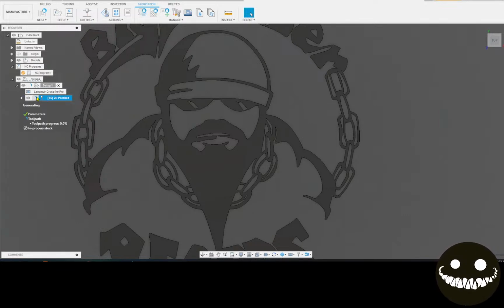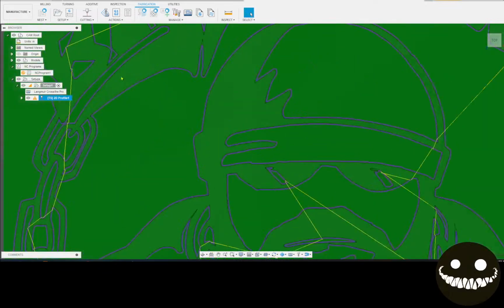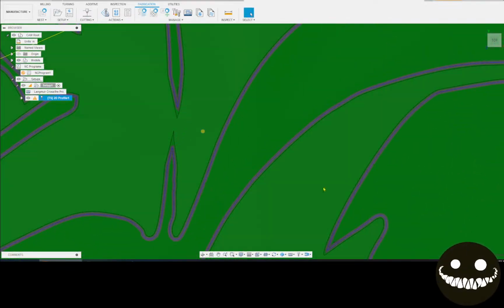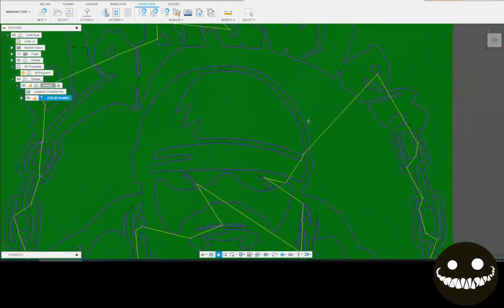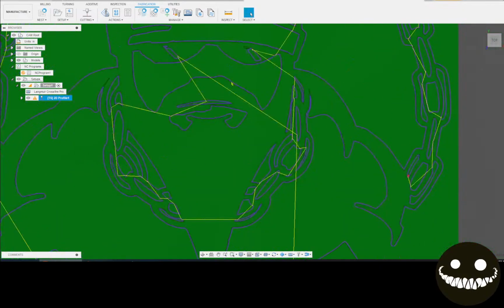Yeah, it usually goes 0, 9, back to 0, and then starts interpreting. And right now it's having a tough time figuring out, but no, it looks like it got past. Chugging along here. All right. So, maybe even a little bit better of a representation. You can see it got a little deeper into these corners here. It still didn't pick up this eye, but it couldn't fit there. You'd have to do a kerf width adjustment for that.